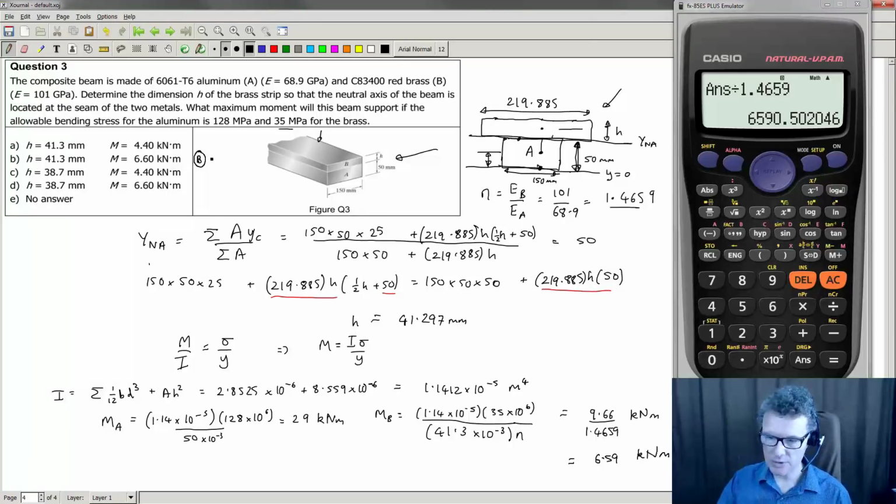Okay, so the bending stress will actually be less than, because this is not the correct model. We have to go back to this model, and the stress that was being experienced, if we imagine this whole thing to be aluminium, is going to be higher than the stress than if this was actually brass. Another way to consider it would be that you're changing the cross-section area, you're scaling the area by the width. So you're scaling it back down by this almost about 1.5 ratio.